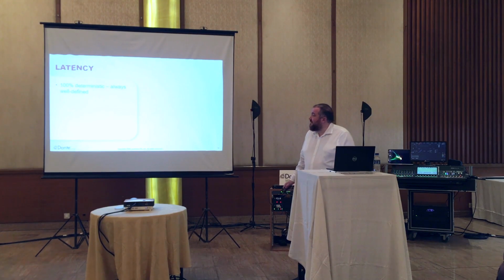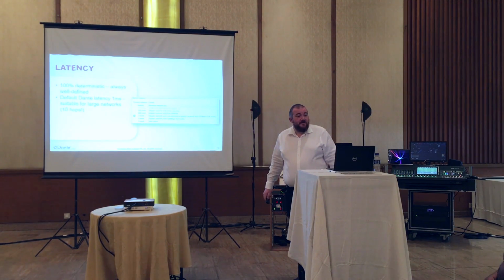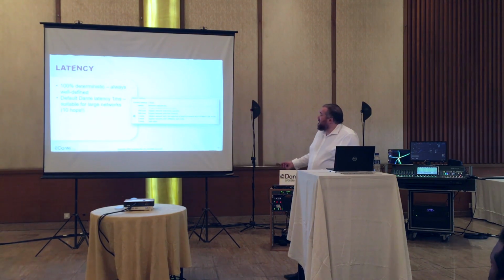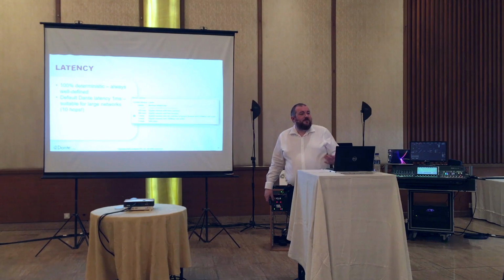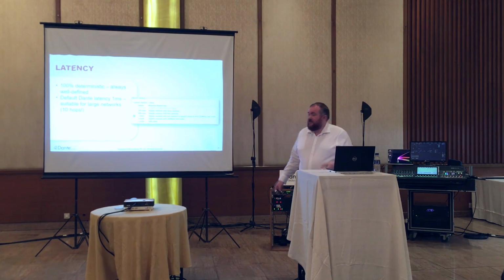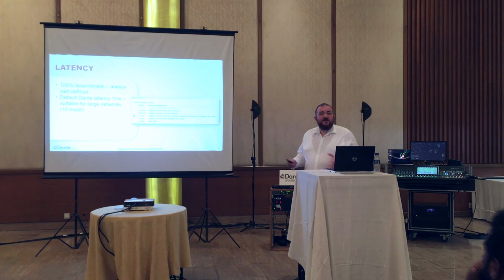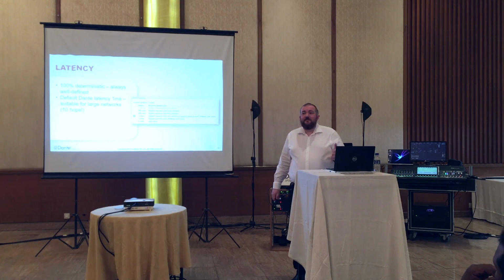So latency is 100% deterministic. It's always well defined. We've changed this on the new Dante Controller. We included this stuff about switches for people who had been using CobraNet previously to have some kind of comfort. We've removed this because now we have the latency monitor, which actually gives you a true view of how fast your network is performing.